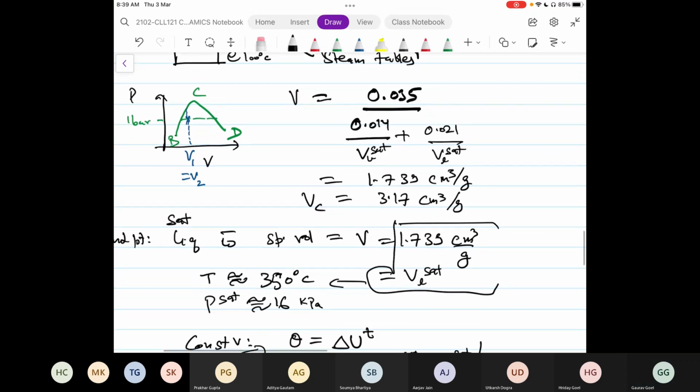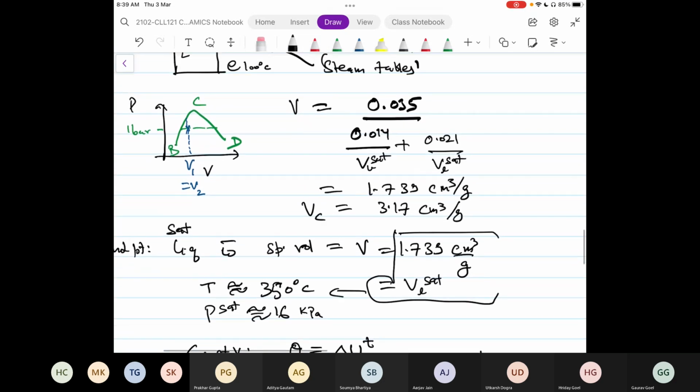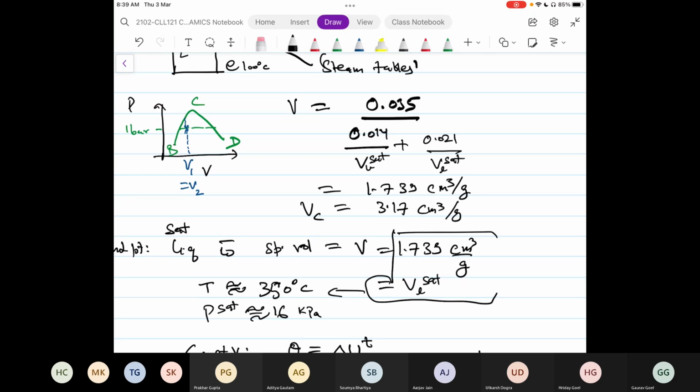Okay, I got it through the diagram that you have drawn, but in my mind I was thinking that if a vapor phase was already present, then if we heated more, it would convert to liquid. So I was not able to get that. Yes, the liquid can, because the amount of vapor was so less. That means the mass contained inside the vessel is very high. If you want to visualize why this is so, the mass contained within the vessel was so high that mass in the vapor state cannot be contained inside the vessel. So therefore, what happened? The liquid expanded and took up the entire space.